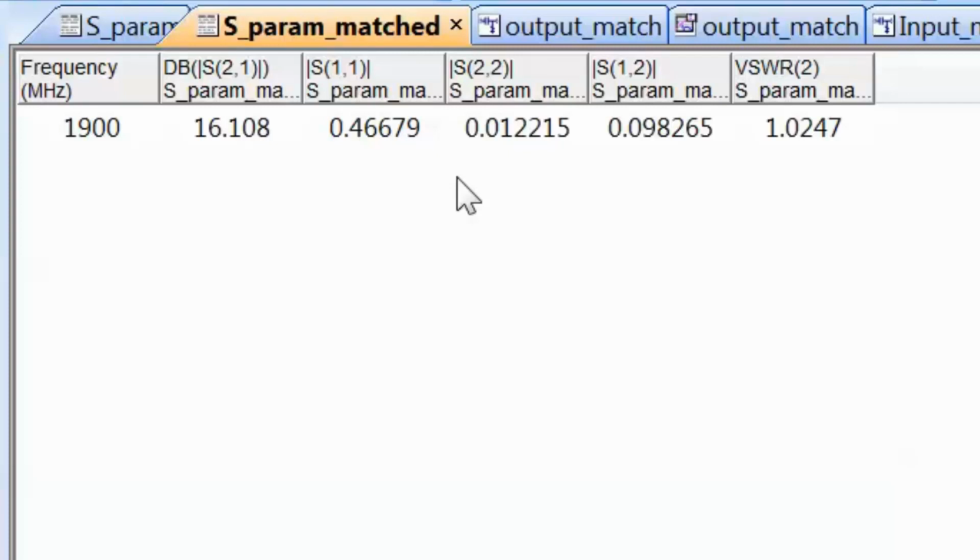And we will be looking at other techniques in the next tutorial, and we'll see how we can use some mathematically worked out values which allow us to calculate the input and output matching networks at the same time, so the calculation takes into account the interaction between the input and output. And you put these two on together rather than one by one and achieve the maximum gain for your transistor. So we'll be looking at this technique, which is called simultaneous conjugate match, in our next tutorial.